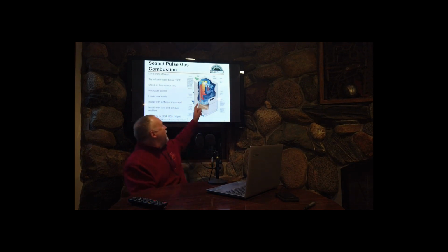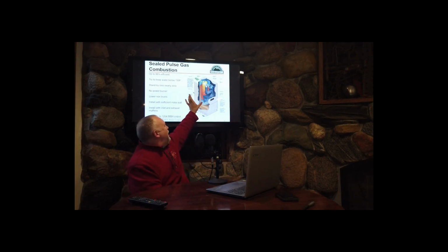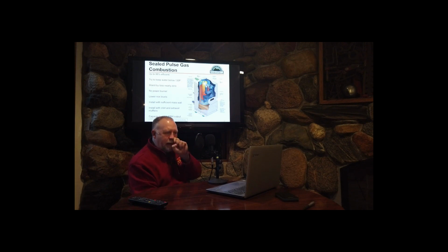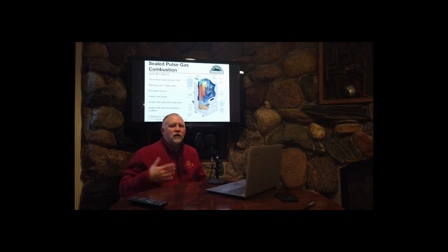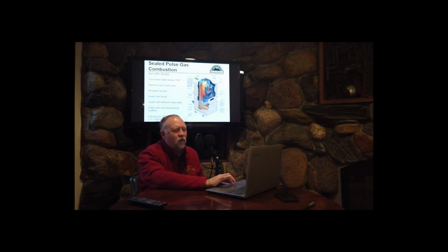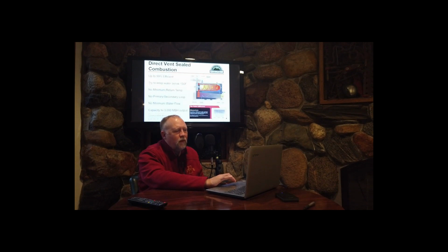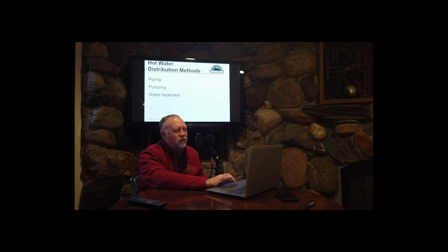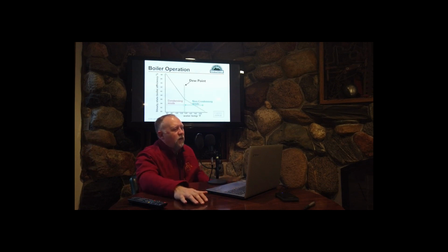I can get greater heat transfer by making this boiler smaller, making these coils as thin as possible, but I am running closer to failure. Think like on one of these, 15, maybe 20 years is a good life expectancy for these high efficiency coil boilers. Here's, we'll just keep going. There's other pictures. All right. We'll talk about water later.